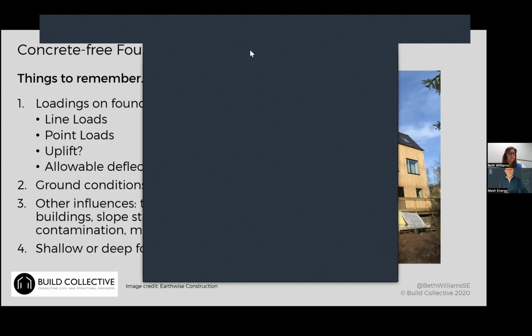There was an interesting project recently which used screw piles, and we ended up using a timber deck on top of the screw piles for the ground floor, as opposed to a beam and block or a steel option. We used timber glulam ground beams and a glulam deck. It was a composite glulam and then a very slim concrete topping floor. So that one was quite interesting.